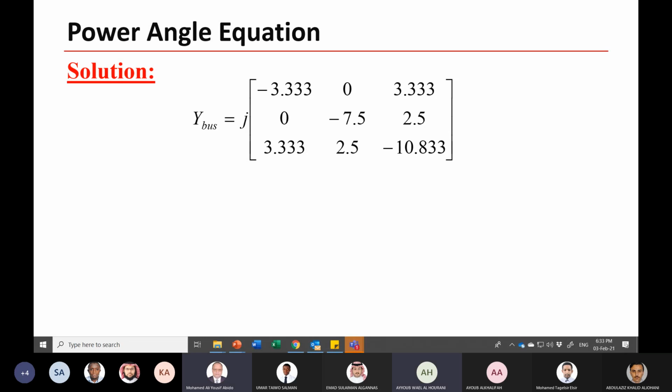Doctor, we are using the transient reactance for the synchronous generator, but I see that we always use transient even for a steady state analysis. So the transient reactance is different than the steady state, or it's always the same? That's different, definitely different. But I see that during fault and without fault, we use the same X prime.